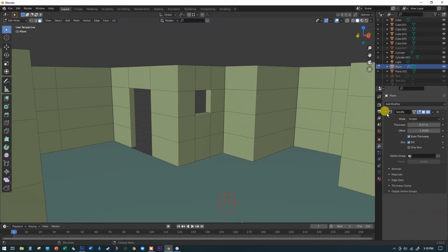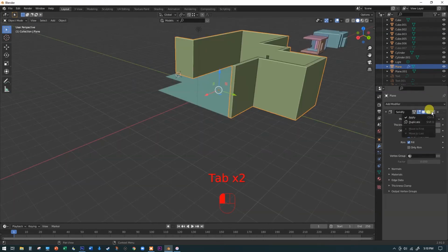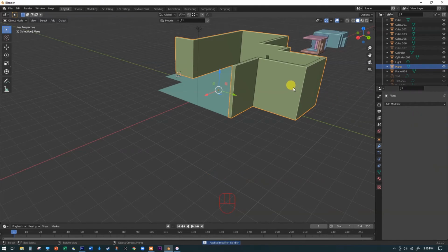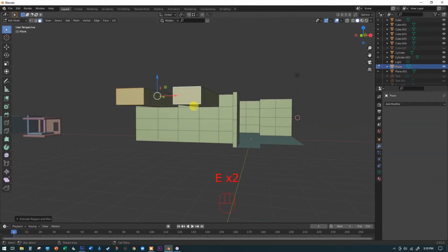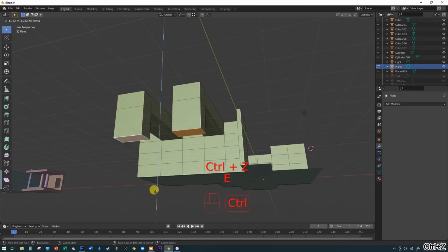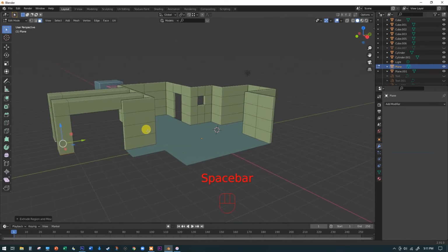But if you did want to apply it, you could very easily then grab all of the faces. It will turn these not real faces into actual geometry. I'm going to hit the Tab key, and I'm going to come in here and say apply. And now all these faces here that weren't really here before are now things that we can actually work with. So I can come out here and extrude another part of our scene really quickly just by using faces that really weren't even there until we applied the Solidify modifier.